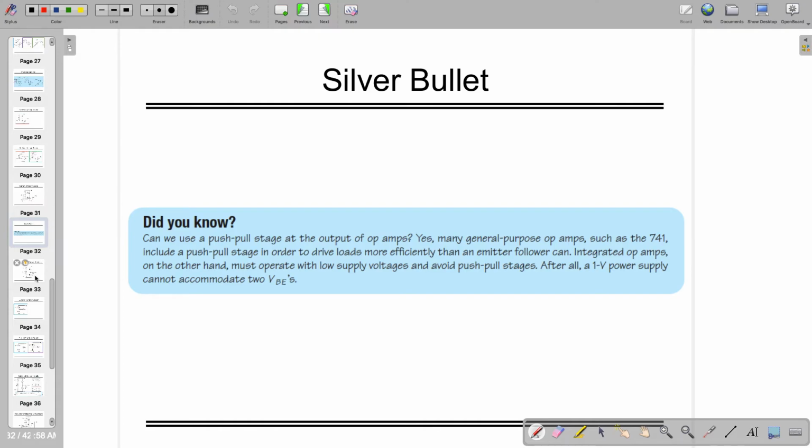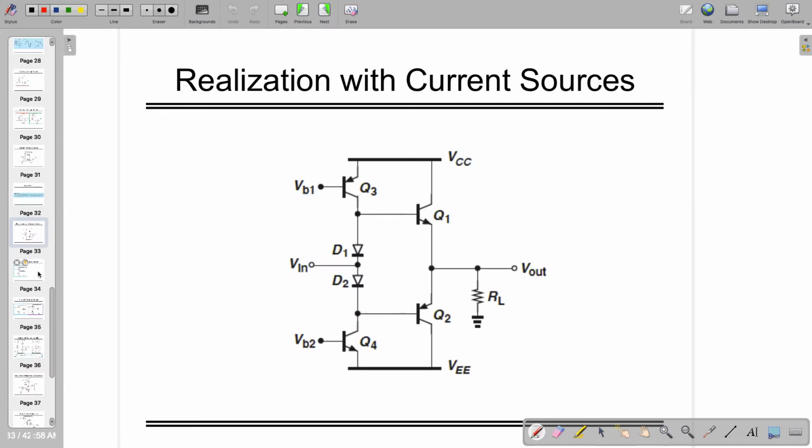However, if it is very low, you need to add one output buffer, which is an ideal stage of voltage control voltage. So that can be done by any push pull stage. Okay, so now what I'm saying, rather than doing this at the one side, let's have two current sources, or one is current sink, one is current source, and you can add both of them.